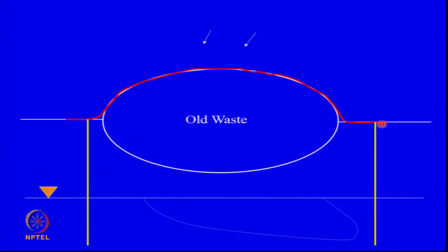To prevent groundwater flow from traveling downwards, I may put vertical cutoff walls. We will look at what these vertical cutoff walls are in a subsequent lecture, how we make them, but these are vertical impermeable walls. Not of concrete, because concrete is rigid. These are more like vertical, flexible, impermeable walls made of low permeability soil, and we'll look at them later.